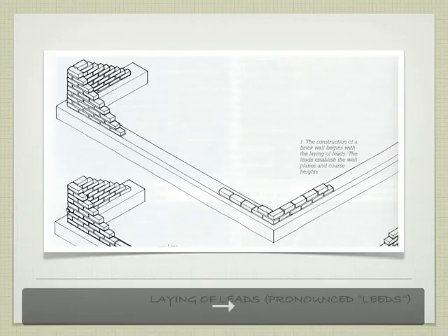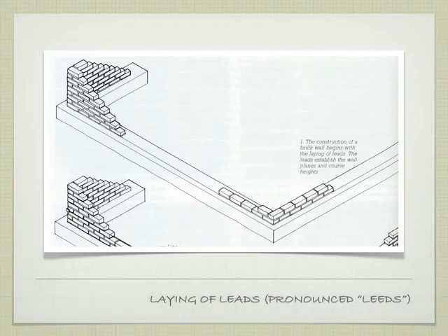So if we were building a purely structural brick building, which, again, I've told you a little bit in the beginning, is very unlikely here, right? Partly because if an earthquake force is acting on a building that's made up of a bunch of little tiny pieces, right, no matter how strong your mortar is, there's an awful lot of joints. So if you have just a few of those joints that aren't perfect, guess what? The whole building will start to crumble, right? Where if we had, say, a concrete wall, it's more of a monolithic building, and it can handle the stresses of an earthquake much better, right?